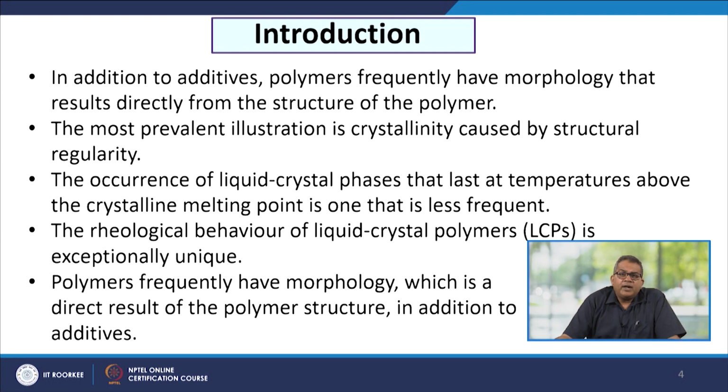Now, in addition to additives, fillers and stabilizers, polymers frequently have a morphology that results directly from the structure of the polymers. So, this makes them more and more complex in nature. The most prevalent illustration is crystallinity. This is caused by structural regularity. The occurrence of liquid crystal phases that last at temperatures above the crystalline melting point is less frequent. The rheological behavior of liquid crystal polymers, LCPs, is exceptionally unique.